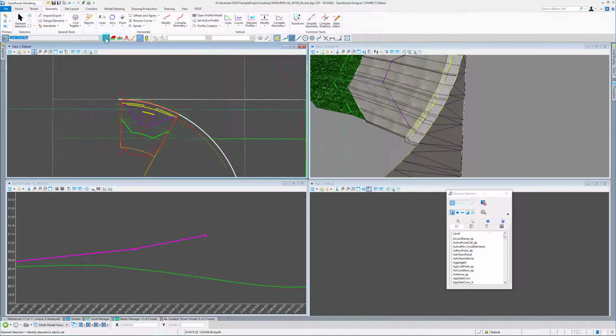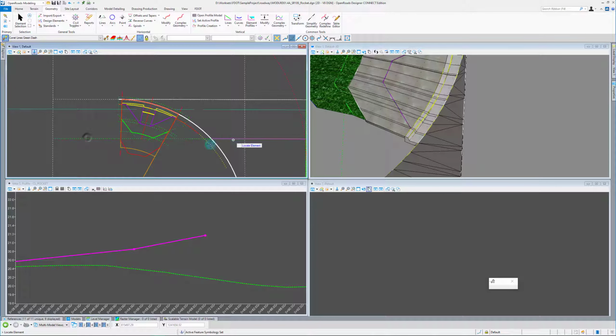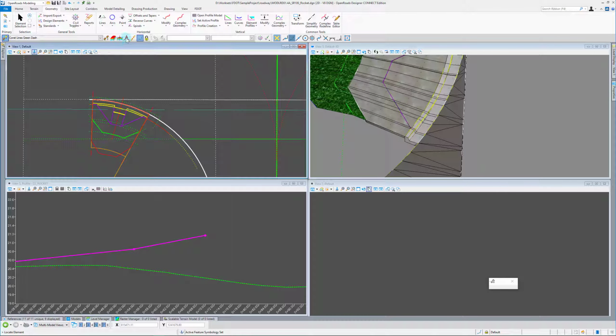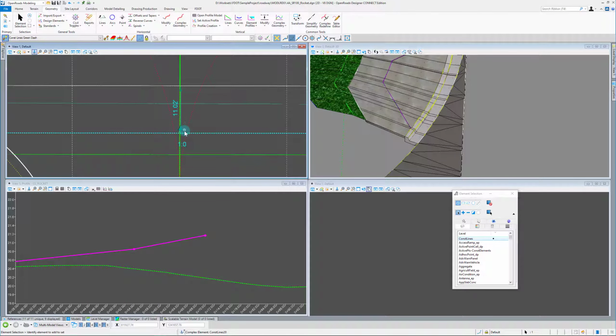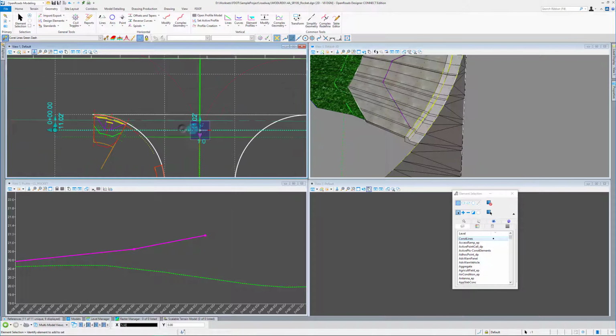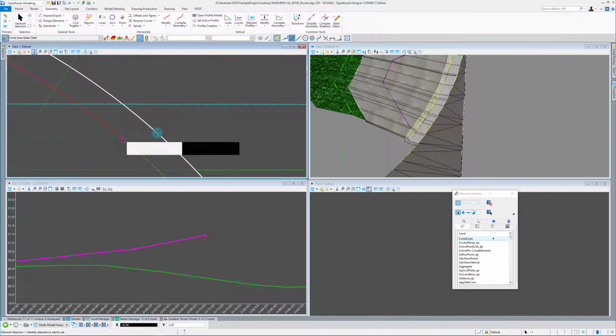And what I'm going to do is create another green dash line that goes across there. Single offset partial. Then I'm going to do single offset entire. And I'm going to hit N to get off here. I'm just going to place it for now. I find that if I want to snap my offset to an end of a line, it's easier just to place this anywhere and then come back and grab your offset and snap here.